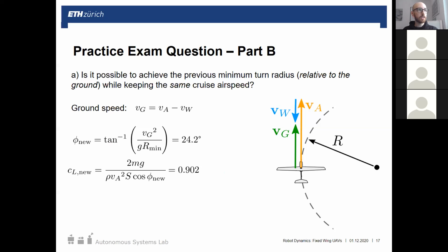And so the definition for the X body axis is quite a loose thing actually. It's just saying out the nose basically is the loose definition for X body axis. And the reason it's loose is because it's hard to say, if you take the main wing, which chord on the main wing do you take?